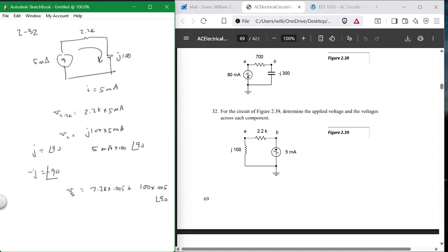Okay, so that's that. Now you say equal, and it's 11 plus I over 2, option down 1 equals. Square and shift, it's 11.011 at angle 2.603 degrees. Okay, so it's equal to what? 11.011 at angle 2.6 degrees. Everybody get that? See how that's done?